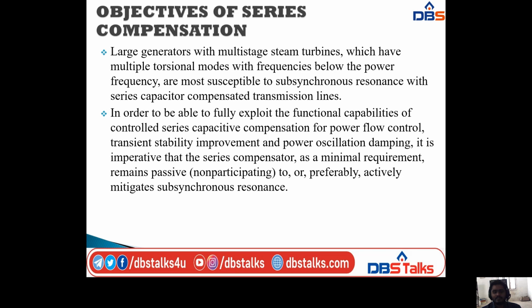Large generators with multi-stage steam turbines, which have multiple torsional modes with frequencies below the power frequency, are most susceptible to subsynchronous resonance with series capacitor compensated transmission lines.